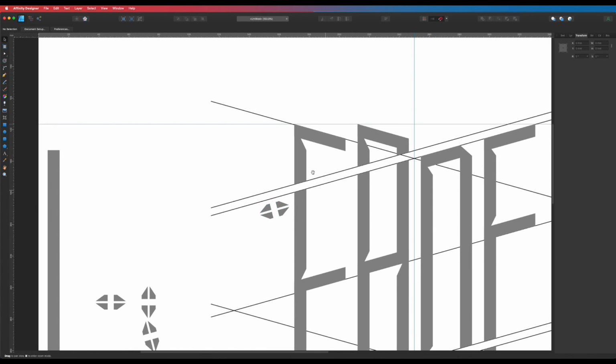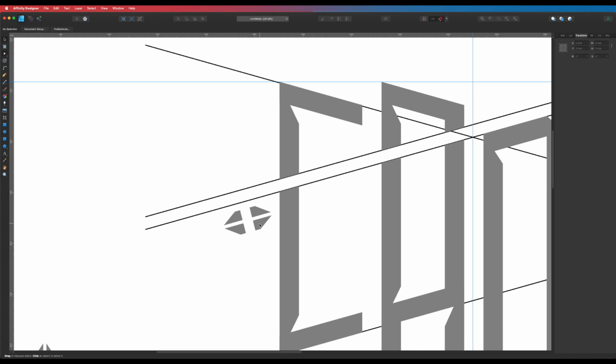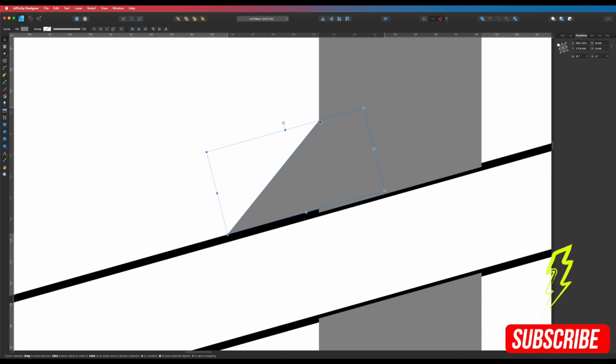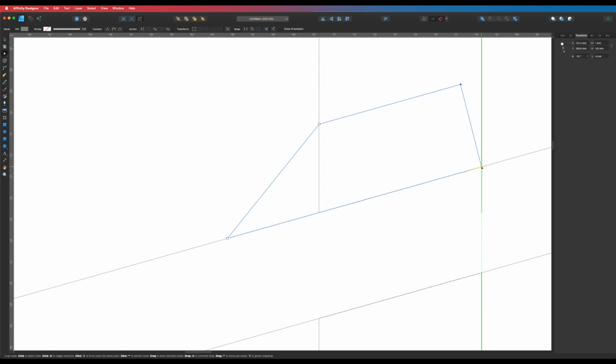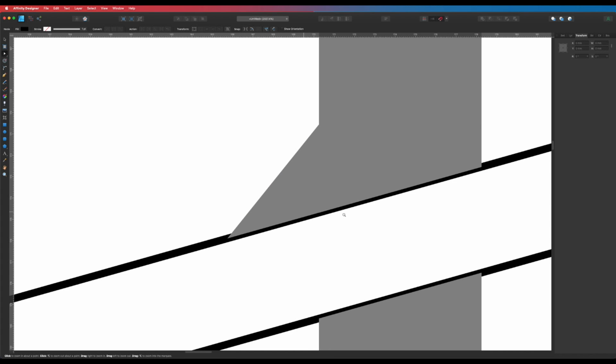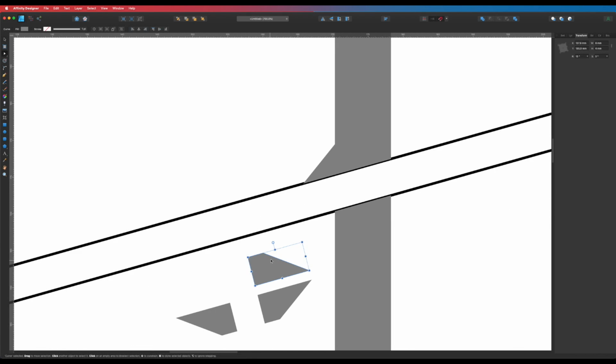These are little elements that I'm looking for right now. So I'm just going to drag this little package with us over here. And I think I'm going to be looking for on the outside. So I'm going to select this one and pop this somewhere around about here. So where this point is over here, I'm going to make sure that goes to our line over there. I'm going to go Command Y, and you can actually see we're going into wireframe mode. So I can click and drag and make sure that everything is perfectly in line. Then I'm going to take these two corners over here, hold down Shift, take those two little nodes, click and drag, snap them to that one, and that's perfect. Command Y just gives you a wireframe so you can see exactly what you're doing, which is perfect. That's what I'm looking to do.